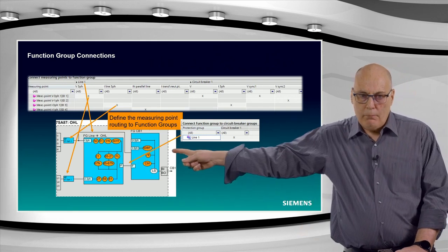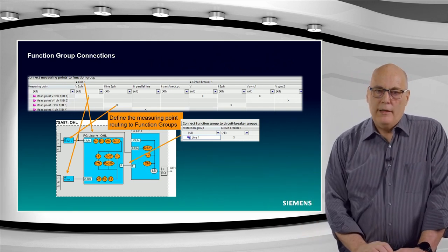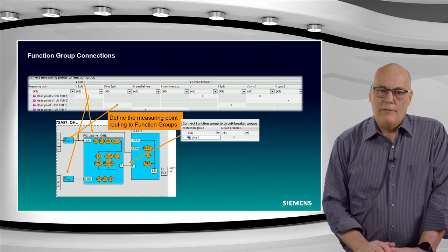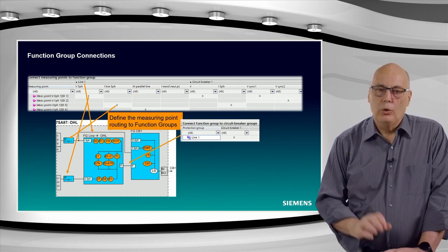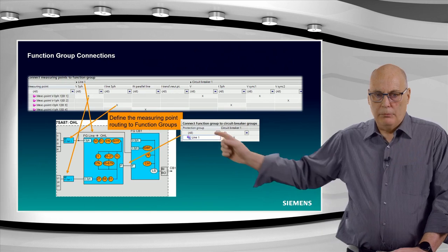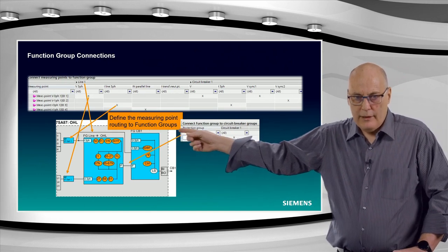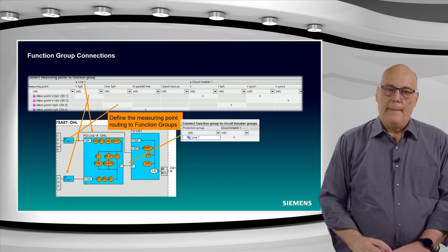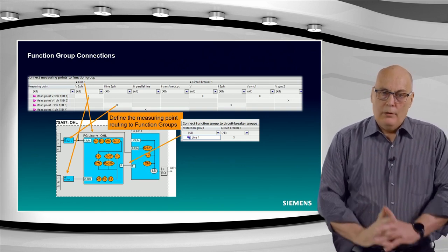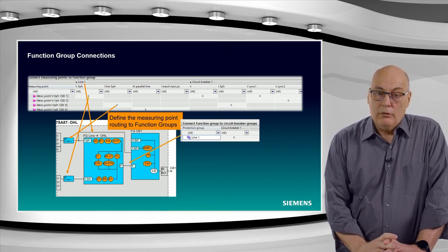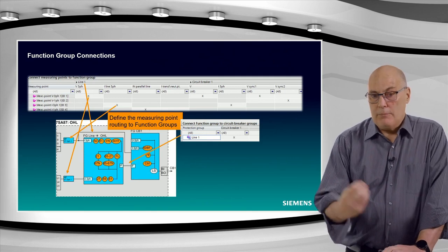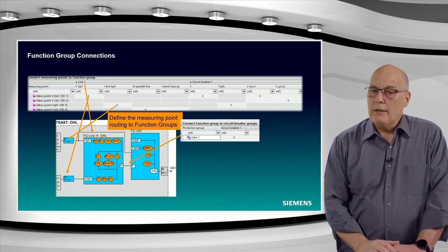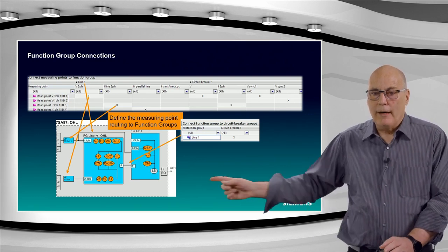And you see that middle blue block there. In the middle there's the 21, our distance protection, and it derives its measuring point from this function group line. As I say, the logical measuring point current, completely on the left there, is used in both function groups, the function group circuit breaker and function group line. The trip command that we route out, and also the feedback, the status, because there are functions in the line that need to know the status of the circuit breaker, that you don't derive directly from the outside.